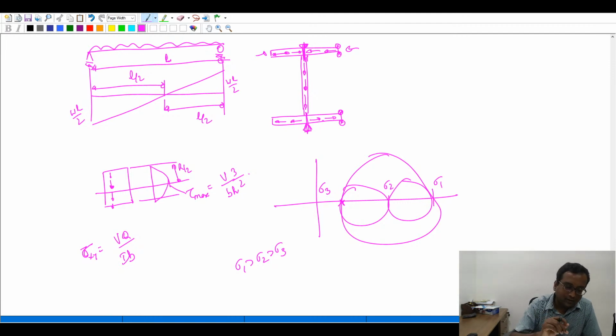The shear force is maximum because in a simply supported beam subjected to a UDL, we saw that the shear force slope has to be a constant. So it can be a straight line moving from anywhere. Okay, but we know from the reaction forces that the reactions at both supports are equal, and hence it has to be that way.